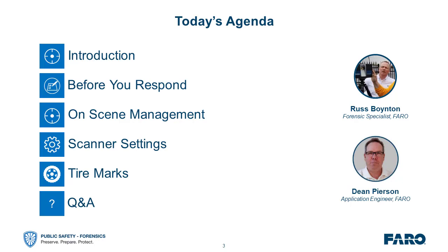So there are, as many of you probably know, 6 ways to do that, at least 6 that come to mind. The most obvious and probably the most often used is to analyze skid marks, measure those skid marks, and then from those measurements determine speed. The next would be a critical speed scuff, maybe a more complicated process if you're doing it longhand, but not as complicated if you're doing it using FARO Zone software.